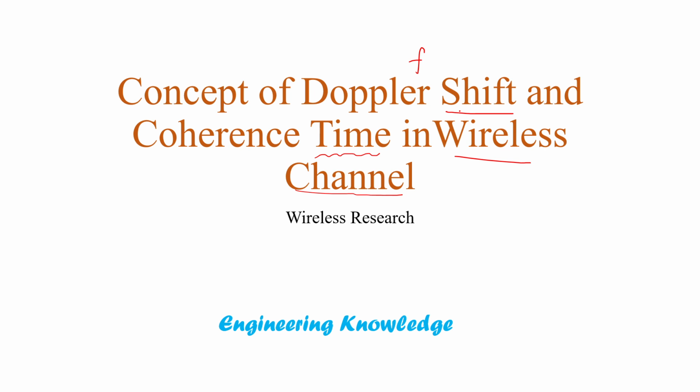There, the multipaths arrive at different time instances, which gives us coherence bandwidth in the frequency domain. The characterization of the channel here is just opposite. There is a frequency shift in the channel which corresponds to the time characteristic of the wireless communication channel.